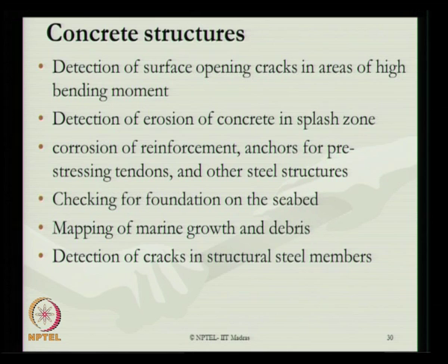So, detection of erosion of concrete in the splash zone plays a very important role, because this gives surface bleaching of concrete near the splash zone, which will initiate corrosion on the rebars. Corrosion of reinforcement anchors for pre-stressing tendons and other steel elements or members of structures is also important to identify in terms of their loss of mechanical strength in due course of time because of the corrosive environment in marine structures.